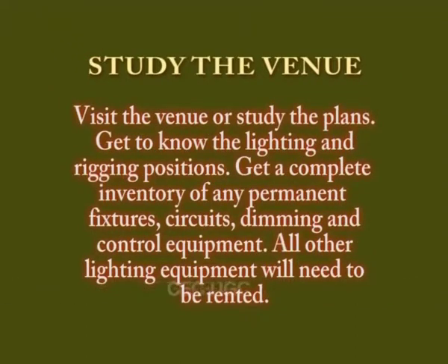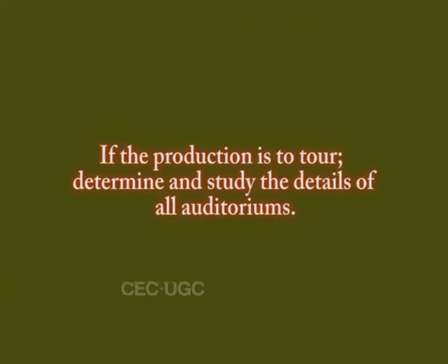Study the venue. Visit the venue or study the plans. Get to know the lighting and rigging positions. Get a complete inventory of any permanent fixtures, circuits, dimming and control equipment. All other lighting equipment will need to be rented. If the production is to tour, determine and study the details of all auditoriums.